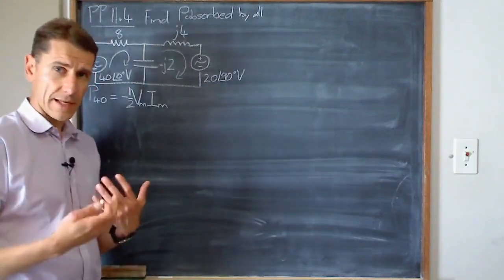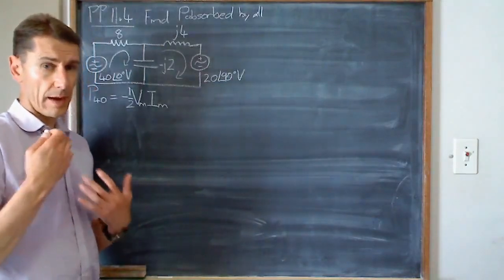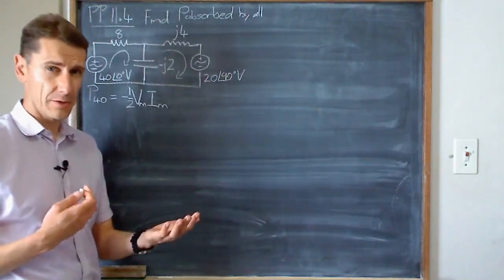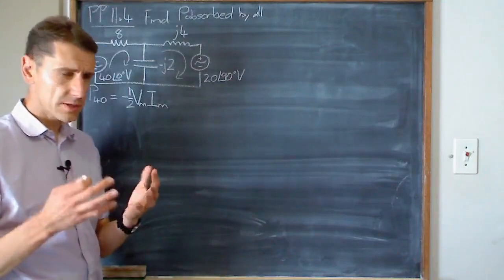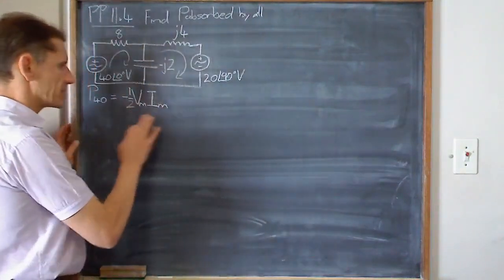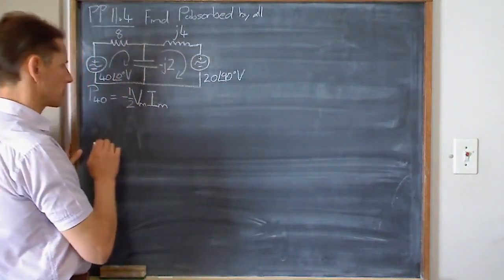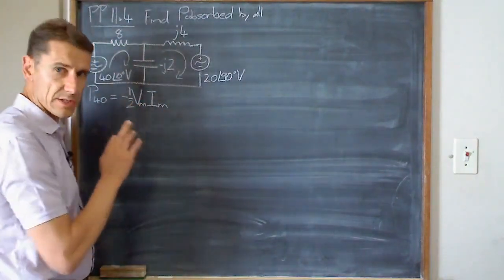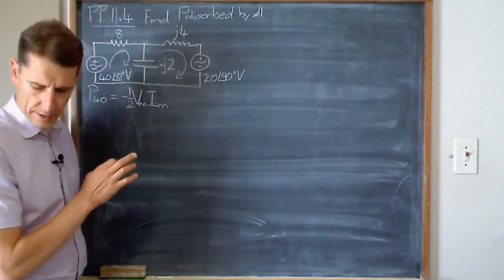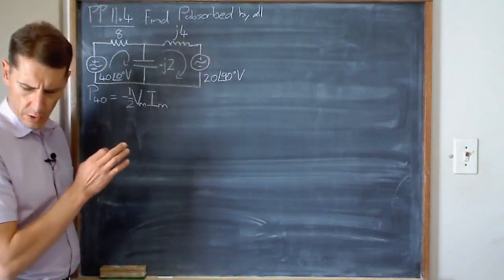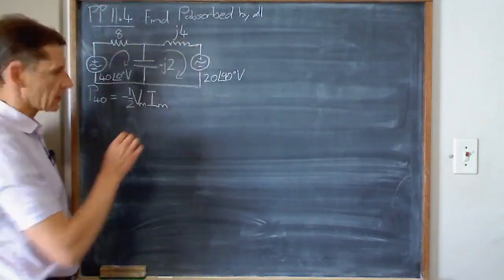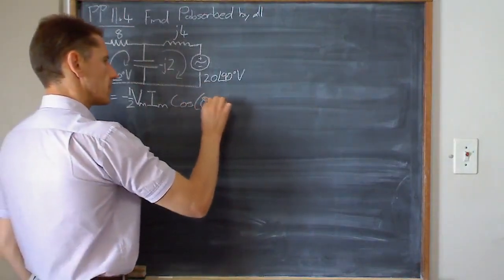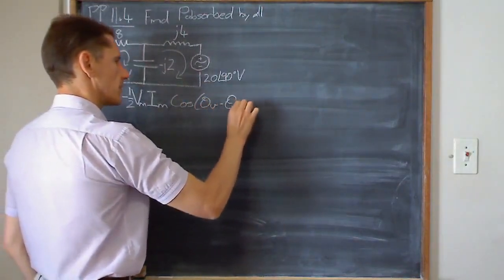But in our next lecture, we're going to move from amplitude to a root mean square, an RMS value. I'm just planting the seed because this equation is going to change a little bit later on. All right, half VM IM, but then there is still something missing when calculating power, and that is your cosine part: cosine of theta V minus theta I.